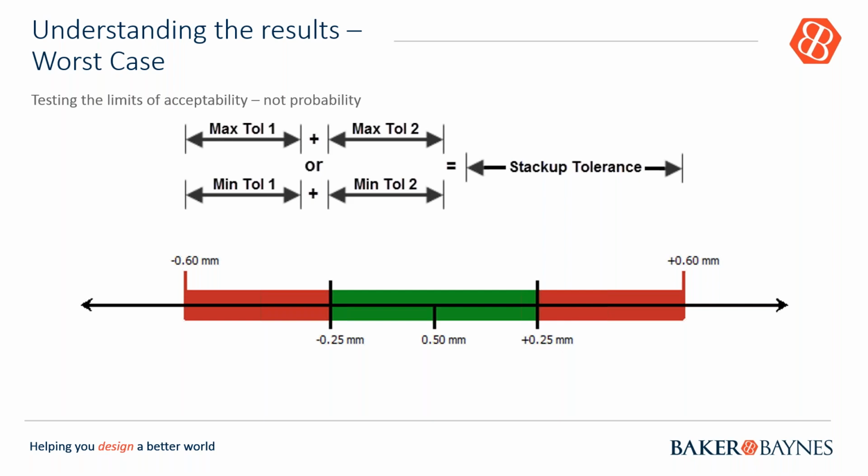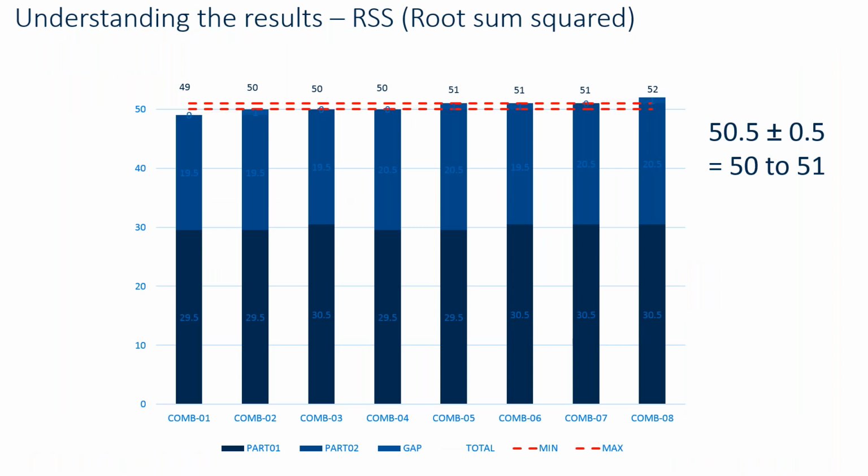Worst case is a blunt instrument; it can lead us to believe that we have a problem. In all likelihood, this wouldn't happen. In reality, few components are manufactured at the extremes of the tolerance requested. In addition, it's unlikely that all the parts manufactured to the worst case tolerance would be chosen to go together in an assembly.